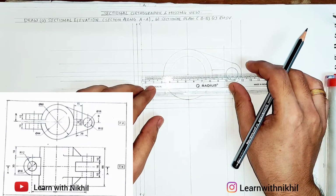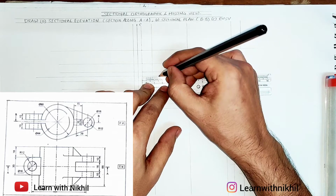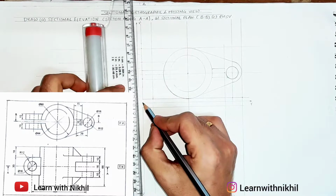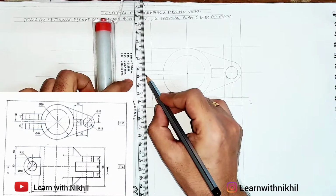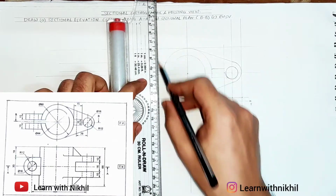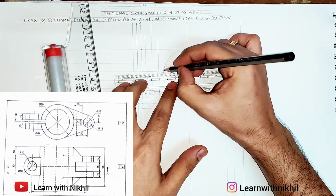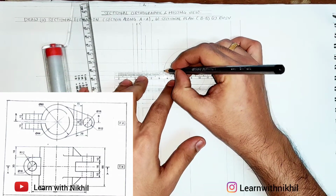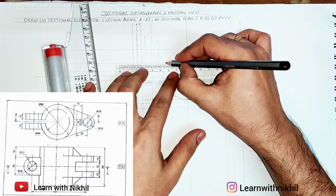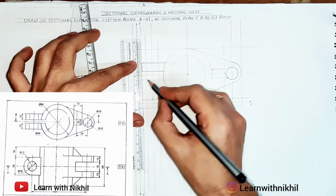There is a hidden circle with diameter as 16. So from the center, 8 millimeters on the right and 8 millimeters on the left. We'll draw parallel lines through it. Now as this is sectioned, this part, the inner circle which is hidden right now, will be visible in the front view. As after the cut, it will be open, it will not be hidden lines. First I'll draw this part dark.